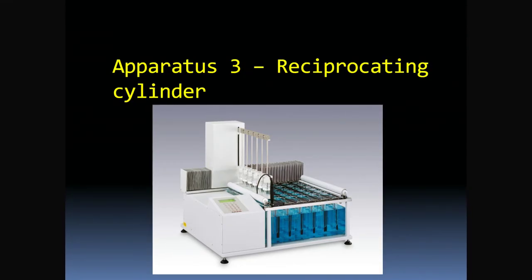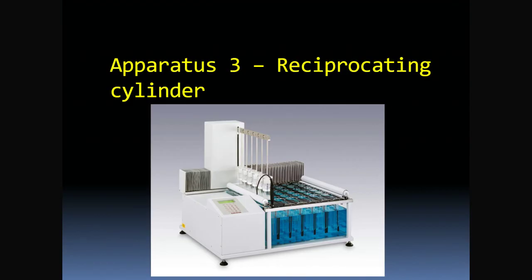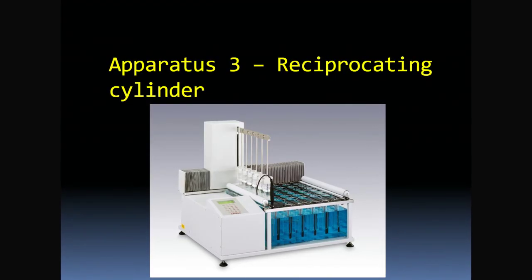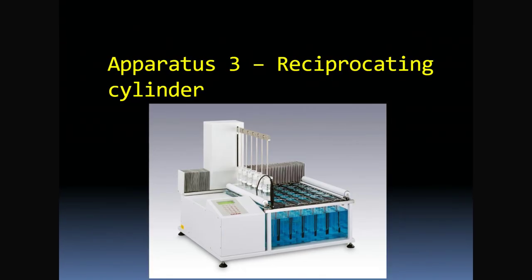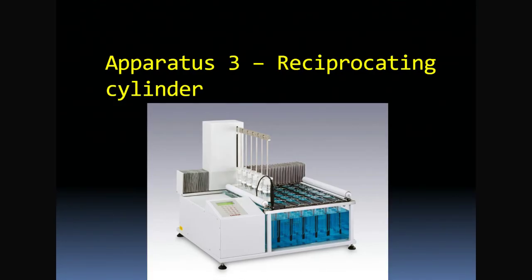This specific hardware configuration allows for a pre-programmed sequence where the inner cylinders move across rows, enabling us to model the entire gastrointestinal transit by transitioning the sample through a series of solvents with varying ionic strengths and pH levels. If we were to increase the dip rate from 20 to 30 strokes per minute, how would the resulting increase in mechanical agitation affect the thickness of the stagnant boundary layer and the subsequent rate of particle erosion?